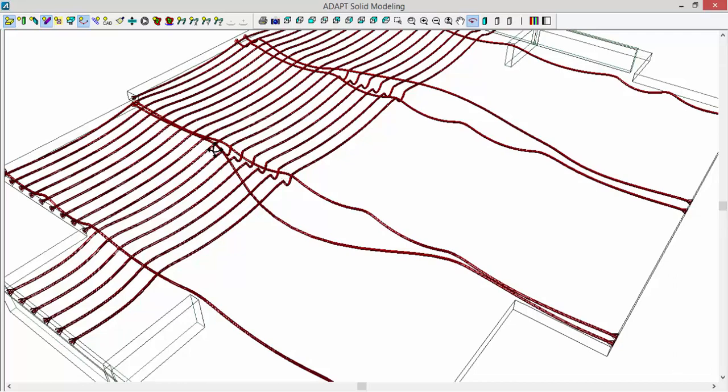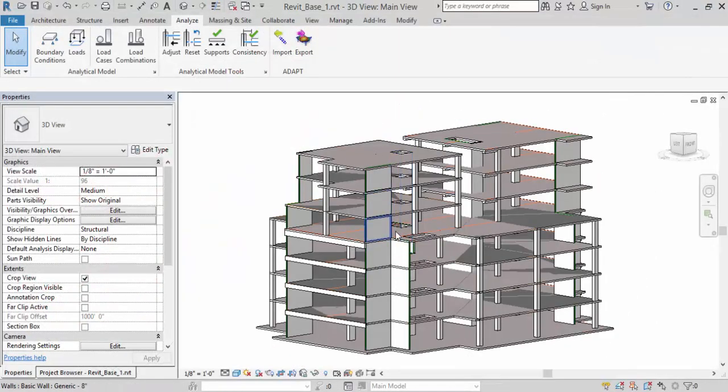And because I never went back and actually changed those spans when I added those 2 points where we had this tendon kind of splitting, you can see the default was a reverse parabola, so it just copied that over. I would have had to go through and change those spans. Okay, so we have that in place.